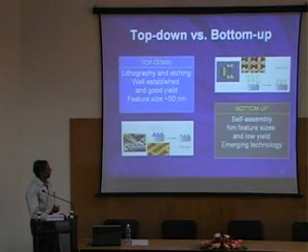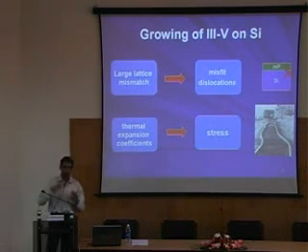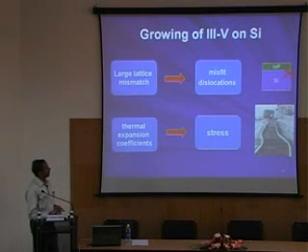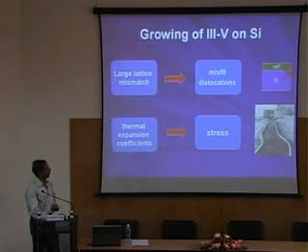There is one more thing that is very, very important. When we want to combine photonics with the existing electronics, it is important that we combine compound semiconductor devices with conventional CMOS technology. But it is very, very difficult because you cannot grow compound semiconductor devices on a silicon wafer because of the lattice mismatch, and that will create huge dislocations and your devices will not work.